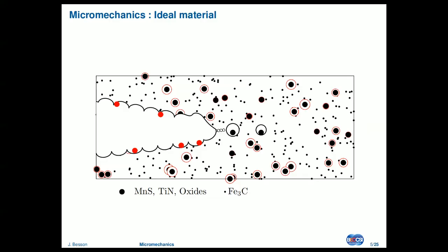But at a lower scale, and these are the small black dots, just to represent that, you have the strengthening particles, iron carbides, so that the material is not too soft. And at these two types of particles, there's a possibility to create damage. So usually, it's very easy to have debonding from the coarse particles, but ultimately, you may have damage at carbides.